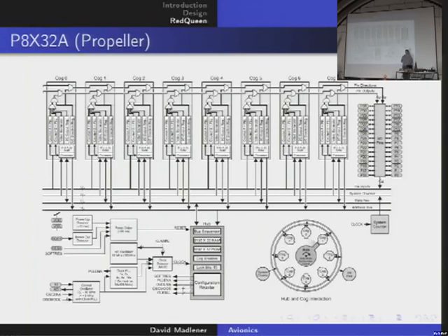And you have one memory of 32K, it's SRAM. Every cog has just a small time to communicate with this SRAM, the main memory, over the hub, and then it switches again. So this hub is always rotating, connecting one cog after the other. But it's transparent to the programmer. You don't see it. You only see that the commands that exchange data with the hub memory will be longer in duration.